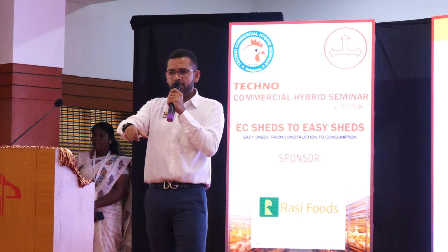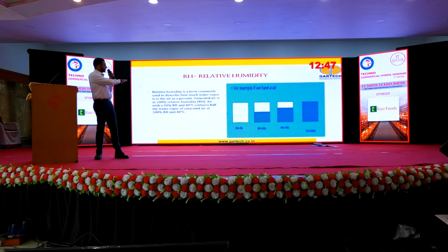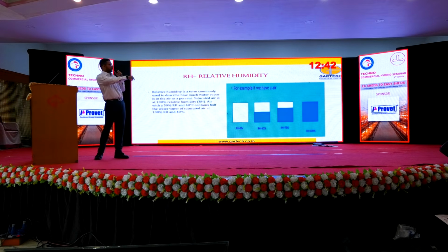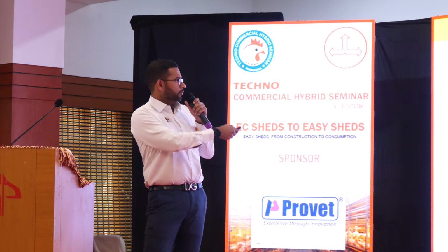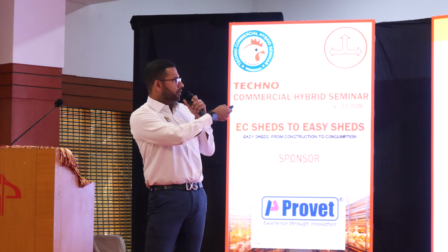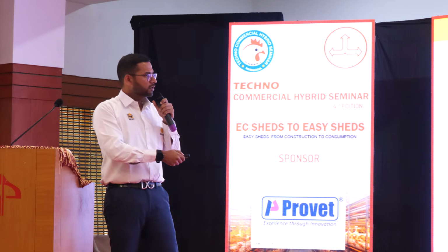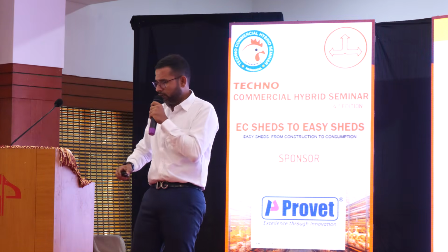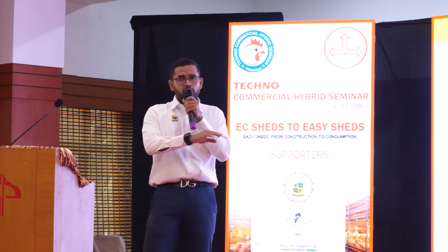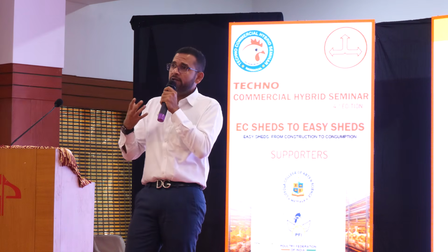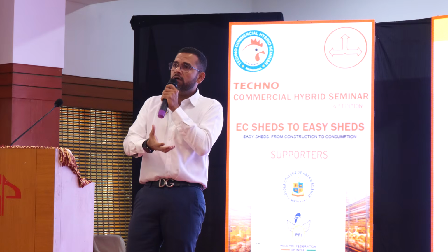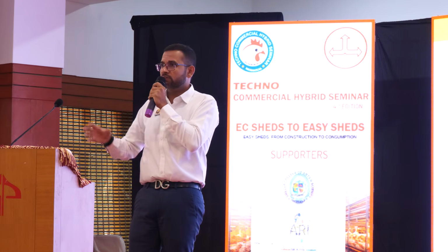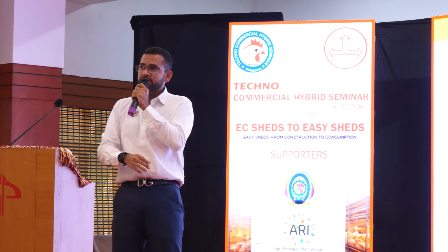So let us see this example that we have. We have one where the relative humidity is 0, 50%, 75%, and 100%. As we saw a little while earlier about the kind of heat losses, we spoke about latent heat loss. This is the most important part. In the latent heat loss, if you have no humidity, that means the capacity of air to absorb the heat and cool the environment in the house down is at 100% capacity.